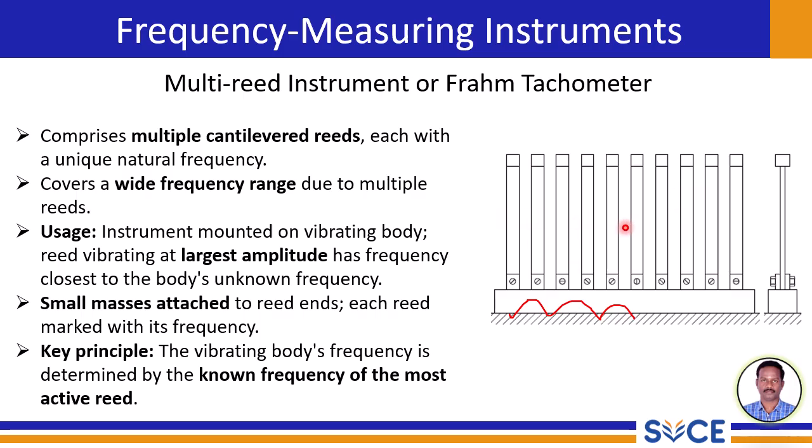Since the reeds are pre-marked with their frequency, identifying the vibrating reed allows us to determine the frequency of the vibrating body itself. This method covers a wider frequency range, due to multiple reeds, than the single reed instrument, making it ideal for broader vibration analysis.